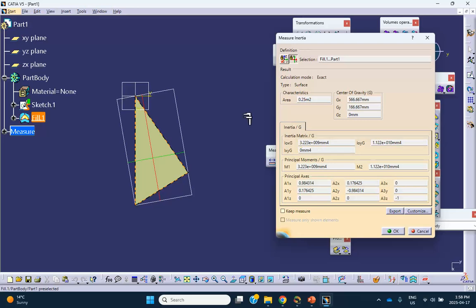Now, one thing you should notice is that when you do 2D section, these principal inertials show you, if the axis selected is at the centroid, you can see that centroid is somewhere here. If it's in the centroid and aligned with these directions, then the product of inertia is almost zero, right there.